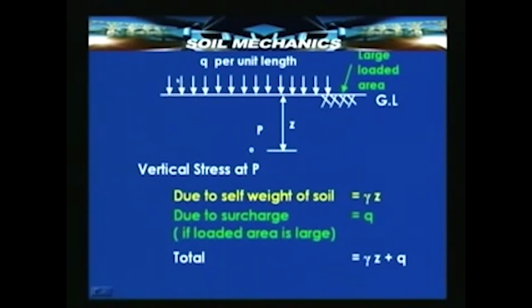Now, we are applying a load here in the form of Q by constructing some structure here. Any activity on the surface, be it the construction of a tall tower, a retaining wall, a building, whatever the structure may be, let us say it imposes a stress Q. Now, as long as this loaded area is very large, at somewhere near the center of this loaded area, the point P is going to experience a stress which is equal to this Q itself.